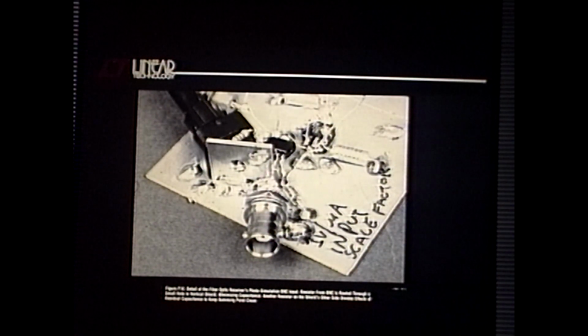Here's the pulse generator input to simulate the fiber input, which is this, which came later. See the resistor going through the hole from the output of the pulse generator input? And then there's another resistor, and then another resistor, and then finally I go into the amplifier. Why don't I just use one resistor here? You know, the shield in the hole, that kind of makes sense. Williams is trying to shield the end of the BNC from getting into the summing point here. But why 3 resistors? Because the shunt capacitance of the resistors is now distributed across 3 resistors instead of 1.